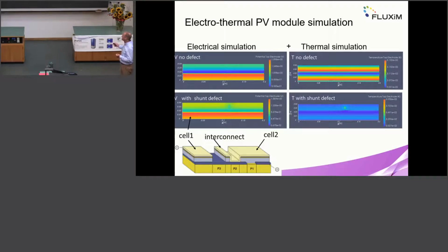So at this edge, we have a small current density, so only little Joule heating generated here, but more on the left-hand side. So again, there's a red edge here. And then the lower example is an assumption of some shunts. So here's a small dark spot, and the dark spot mimics an electrical shunt between the top and bottom electrode. And that means that a lot of current goes through that shunt. And in the end, we will observe an elevated temperature here.